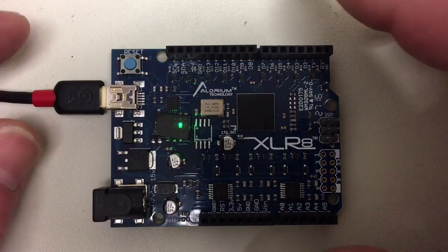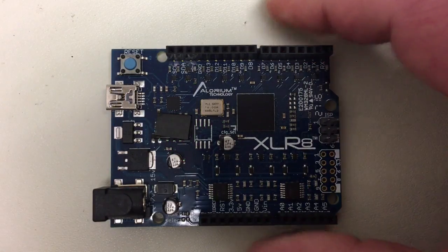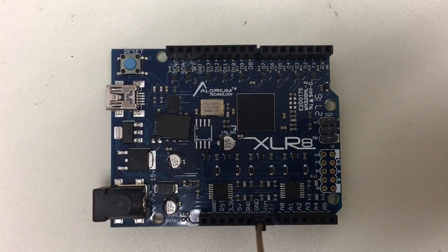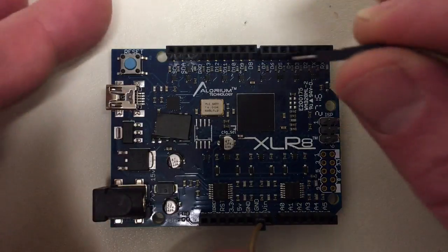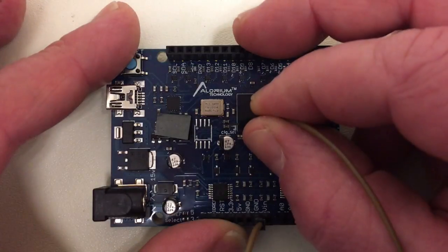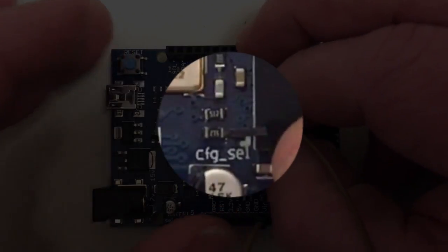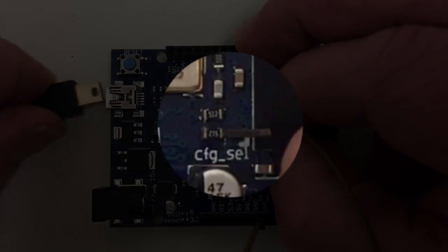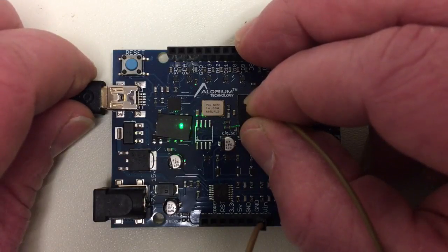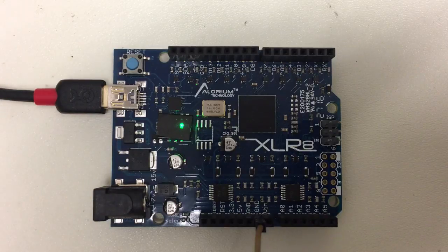The very first thing we're going to do is unplug the board because the configuration image is selected at power up. The first step is to take one end of the jumper and connect it to ground. And then we need to make contact with the configuration select location, which is right on the end of this resistor. It can be a little tricky to do, especially with this camera in the way. I'll get it in place and then I'll zoom in with the camera so you can see. Then we plug the board back in to provide power. It only takes a momentary grounding for the FPGA to select Image 0, so you don't really need to leave it connected for very long. In fact, I probably held it longer than necessary.